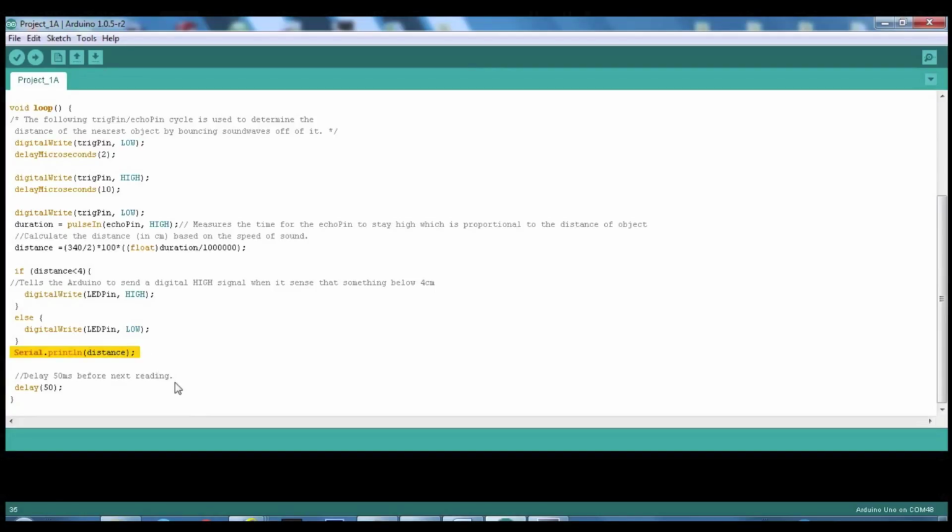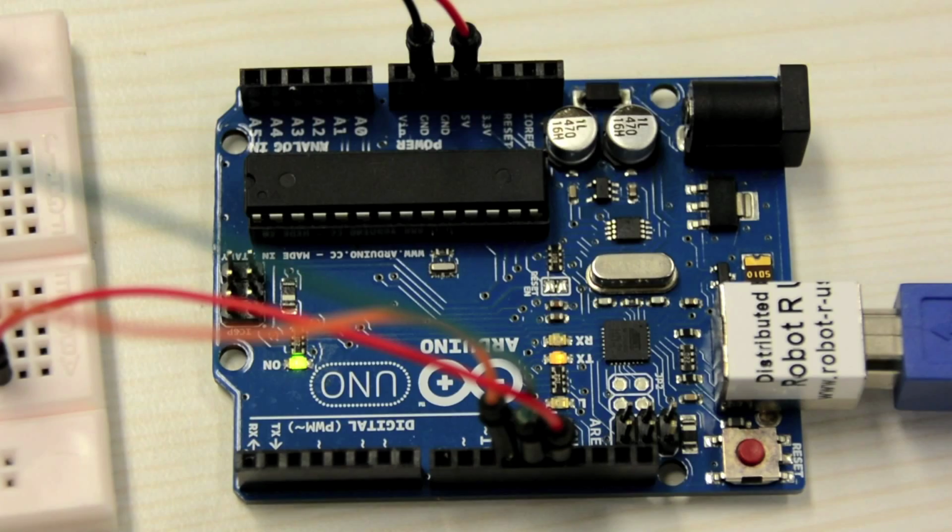7. Serial println. For a more user-friendly approach, we also want to know what the distance is when we are monitoring. So we do a serial print in our serial monitor. We impose a delay after the print so that we can make the prints eye-friendly. Upload time!